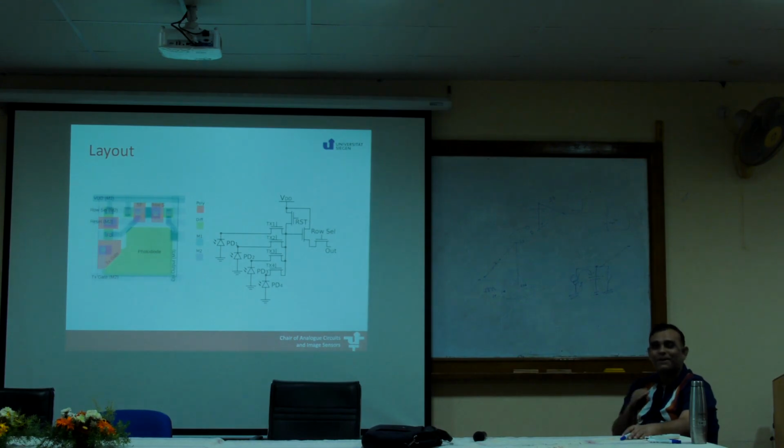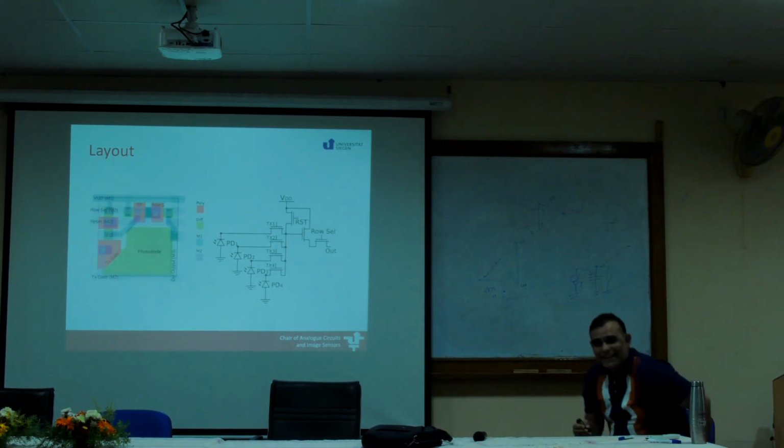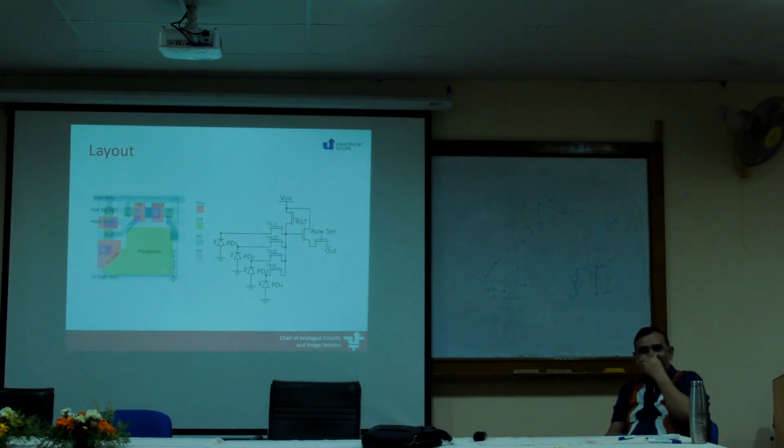And you will see such papers written very fancifully when they say 1.75 or 1.5 transistors per pixel camera, which looks very strange. How can you have a 0.75 transistor? But here we are sharing it between 4. Had we shared between 8, our transistor count per pixel would have gone even lower.